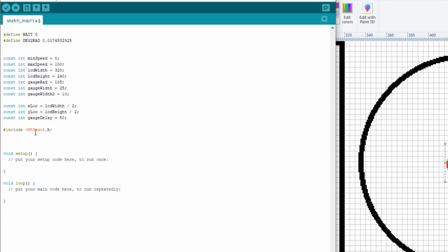So we're going to do a TFT_eSprite. This TFT_eSprite, again, I mentioned that the Sprite.h library was an adaptation of the TFT_eSPI sprite library. So that TFT_eSprite is going to be what we're using to define the sprite objects.